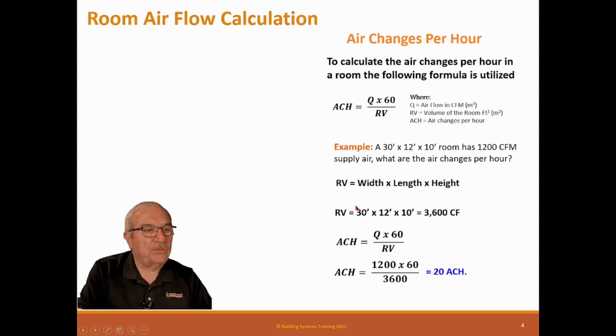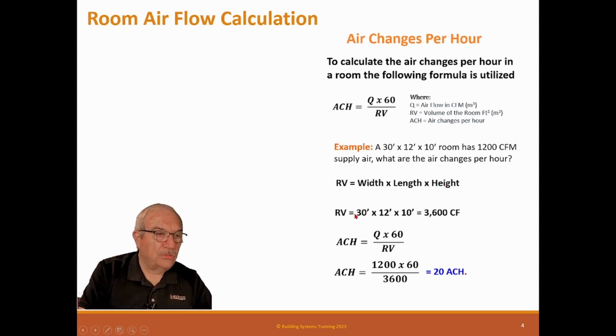Now, why we ever do that calculation is there are certain codes that require certain rooms to have certain air changes per hour, and operating rooms are one of them. There are other rooms, but air changes per hour is what you're looking for.